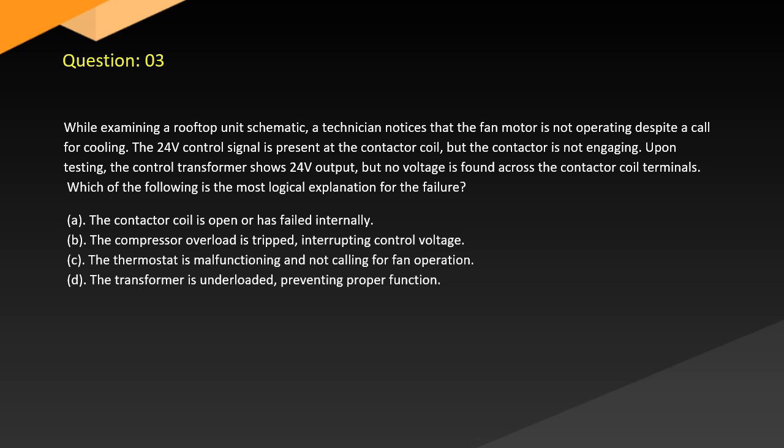A. The contactor coil is open or has failed internally. B. The compressor overload is tripped, interrupting control voltage. C. The thermostat is malfunctioning and not calling for fan operation. D. The transformer is underloaded, preventing proper function.